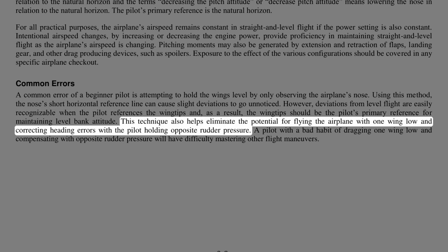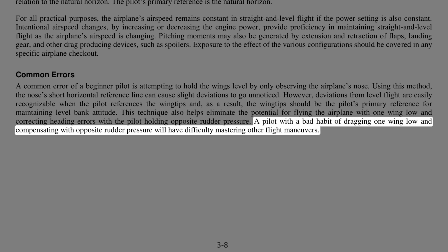This technique also helps eliminate the potential for flying the airplane with one wing low and correcting heading errors with the pilot holding opposite rudder pressure. A pilot with a bad habit of dragging one wing low and compensating with opposite rudder pressure will have difficulty mastering other flight maneuvers.